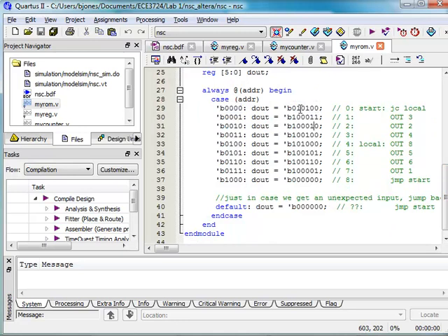And as you know, that is broken into two top words. That's the instruction 01, which is a jump conditional, and then it's jumping to address 0100, which is location 4. Notice that the location here is at address 4, so this is a jump conditional 4, and out to the side we put comments because otherwise the bits are not very human readable. Okay, so we've got all that down. This is what you'll need to modify to change your program and put in your own ID number.